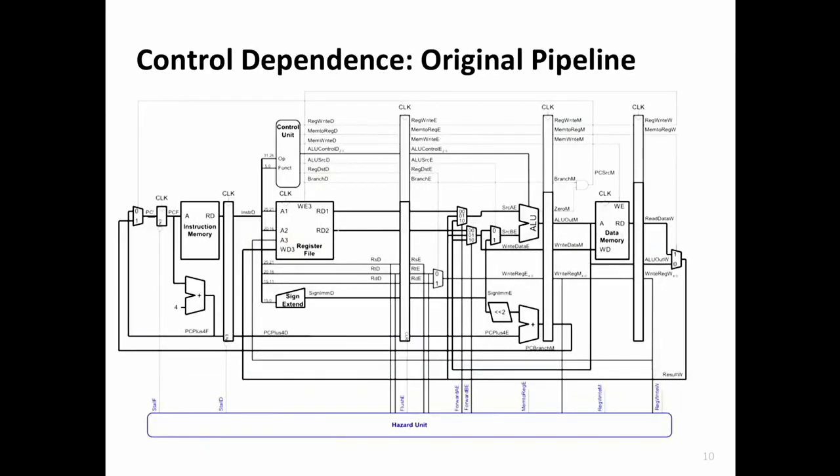So instead of determining the branch over here, let's add some logic early on in the pipeline over here to determine the branch over here. If you determine the branch over here, if you have a misprediction, only this part will be wasted, right? So ideally, you would like to determine where the branch goes right in this stage. When you fetch the branch, while you're fetching the branch, you need to say the next target address should be the target, or next sequential instruction. So really, when you're fetching the branch, you need to do this prediction. That's why this is very tight.